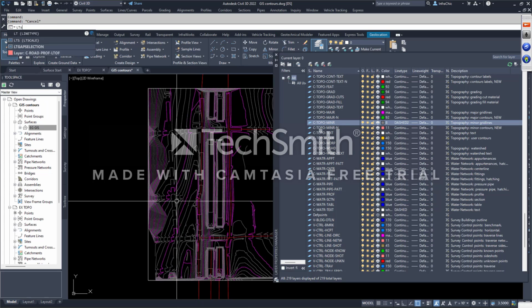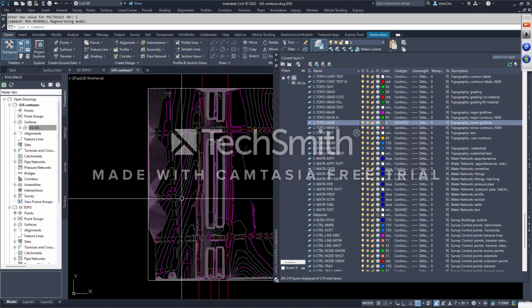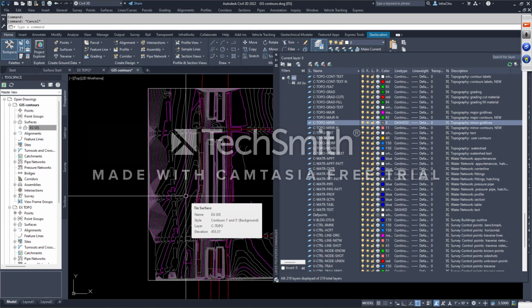If I check my LT scale, it's set to 1, MSLT scale, set to 0, PSLT scale, try that 0. Try regen, doesn't work. Go back to PSLT scale, go to 1, regen, doesn't work. All right, so I'm not going to have awesomeness. That's fine. I can show you another one where I have it dashed. Not a big deal. Happens, sometimes it doesn't take, sometimes it does. Surfaces are tricky. Okay, let's be honest.